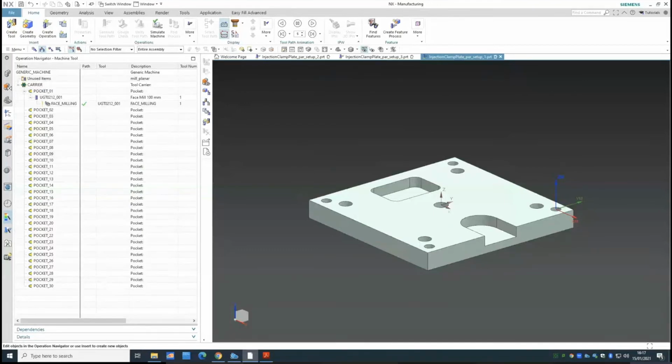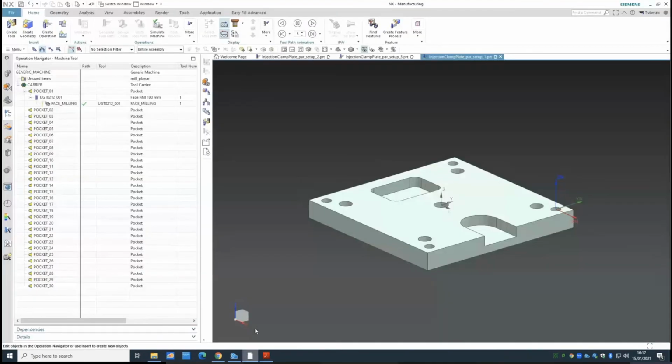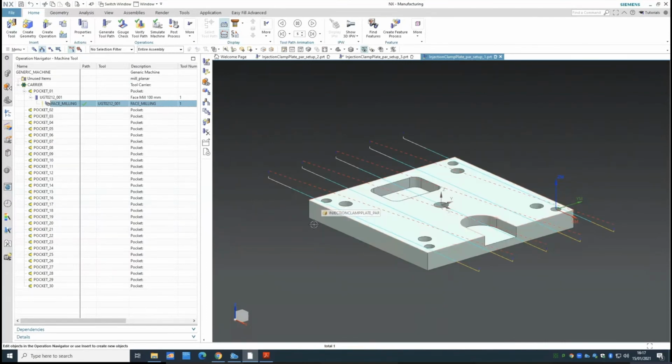And so now we've done the operation, but we went completely with the default one. We haven't defined anything yet. Something that's important, even from last year, probably you remember, is called the feeds and speed. What does it mean? It means that every single time, let's say if you want to do, for instance, the drilling, every single time you drill, there are different things you need to consider. How fast the spindle would spin, how fast the tool needs to rotate, and how fast you need to go between the different points, the different holes. And this is something that you intentionally do whenever you do, for instance, drilling on the wall or something like that. So in here, we just decided to go with the default.